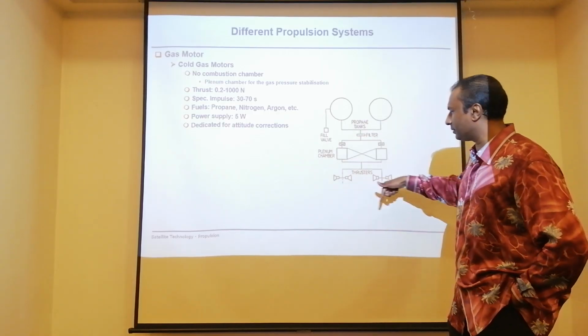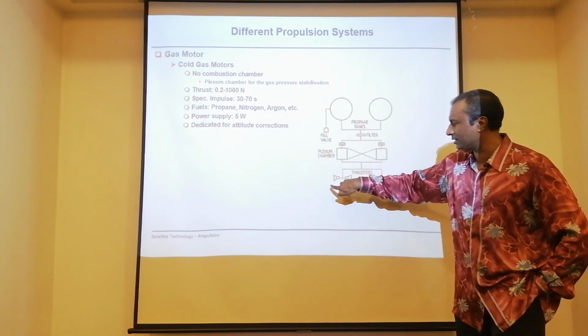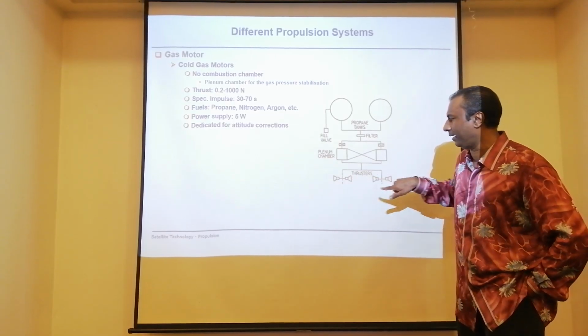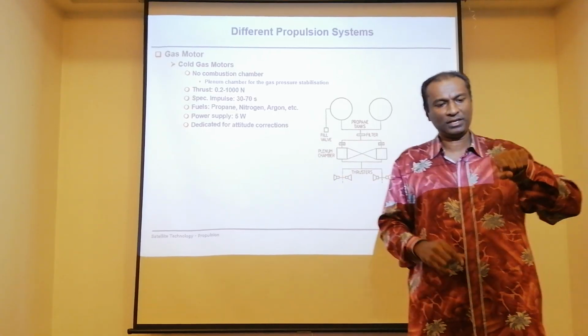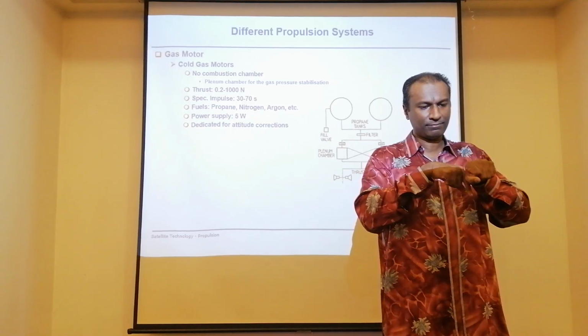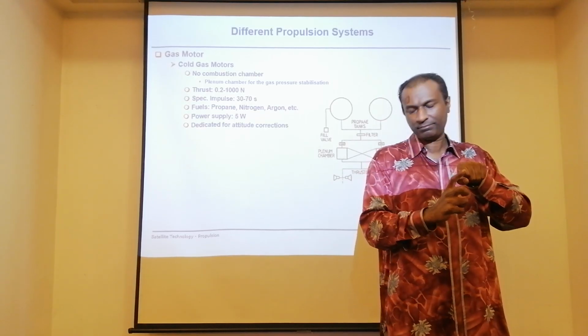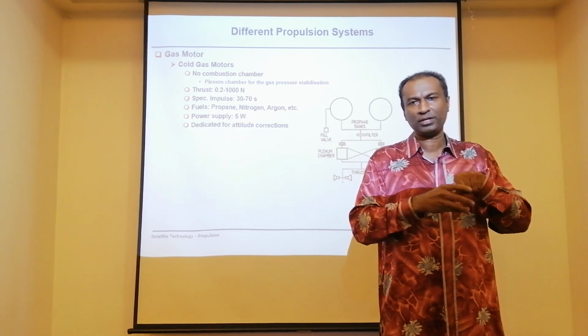It's a simple diagram. Note these thrusters, you see every time they come in pairs. If you want a rotational motion, you must have a pair. Just like what I've said, if you want to rotate this body this way, you must fire up and fire down with the same thrust, that means the same Newton, then you can actually rotate this rigid body.